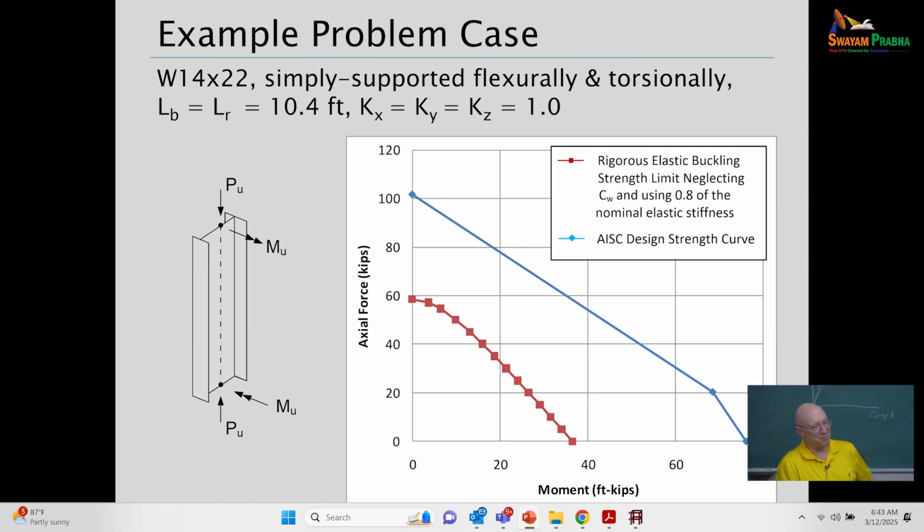So you set up, you run your structural analysis, a 3D analysis. You look at this. This member doesn't look too out of the ordinary here. And your analysis comes back, it's failing and saying that you've got significant elastic buckling of your members at a very low load. Why? Because you didn't include the warping.